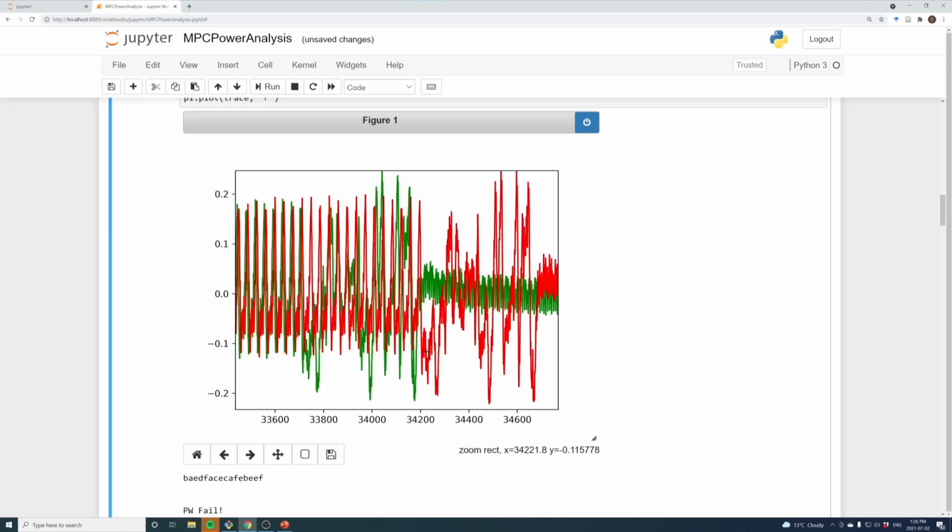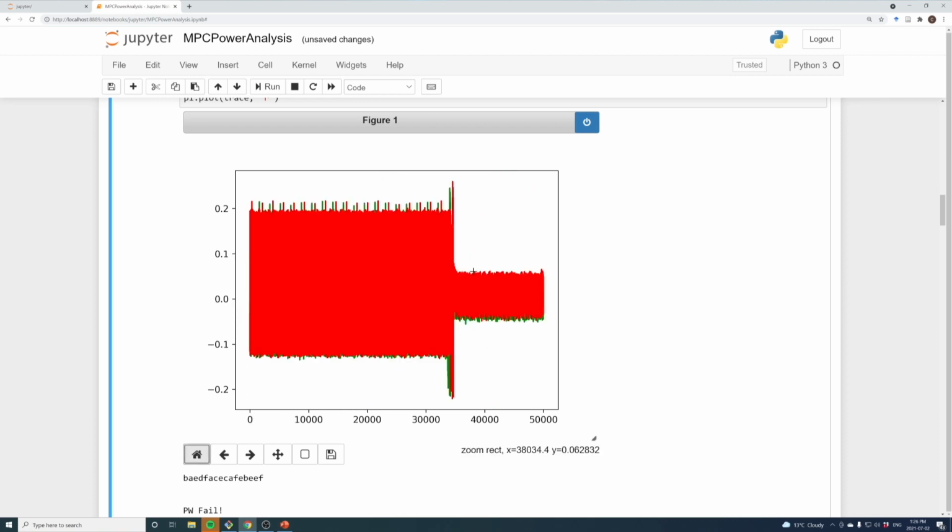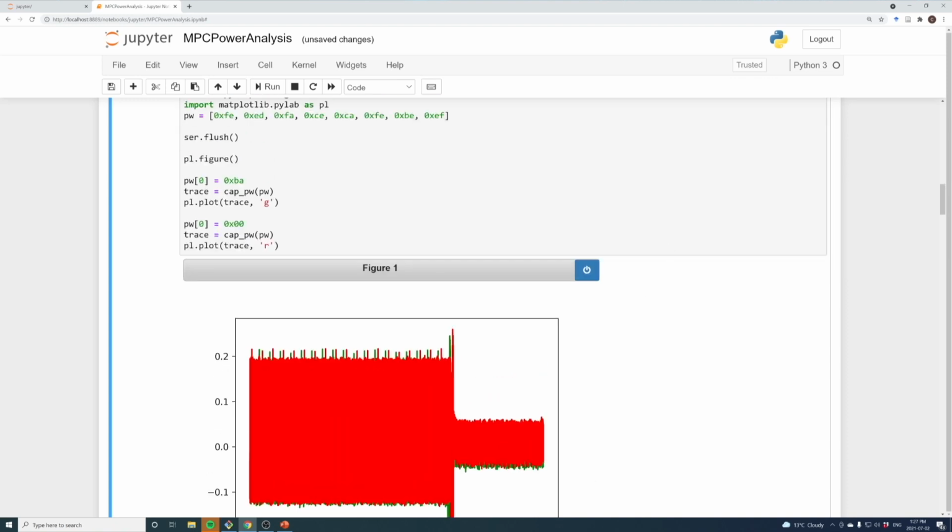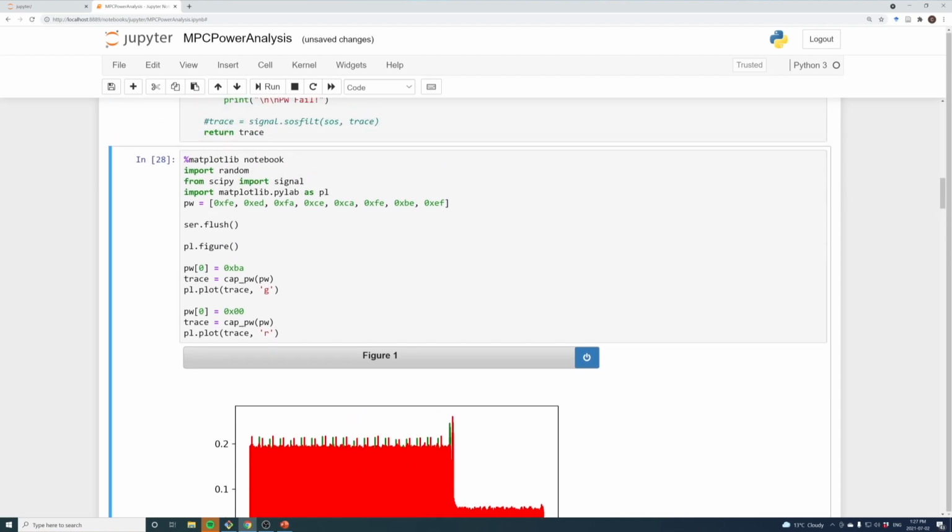The issue is that it's a 64-bit password. You have a limited baud rate, so it's 24 kilobits, which this serial console is running at. Basically, it's fixed. You have a 64-bit password, and it's not just ASCII. You can actually send any password you want, almost. So you have quite a big search space. If you were to brute force this, it's not super trivial. If there's a per byte timing attack, you may actually have something more useful there.